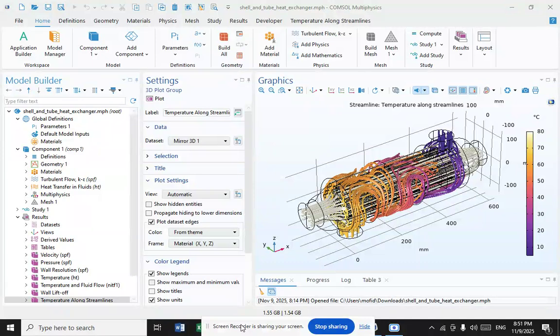To conserve energy and cooling capacity in chemical and other plants, regenerative heat exchangers can transfer heat from a stream that must be cooled to another stream that must be heated, such as distillate cooling and reboiler feed preheating. This term can also refer to heat exchangers that contain a material within their structure that has a change of phase.